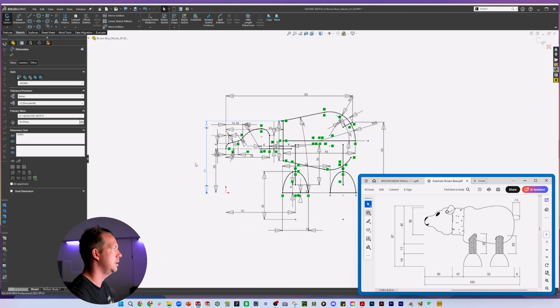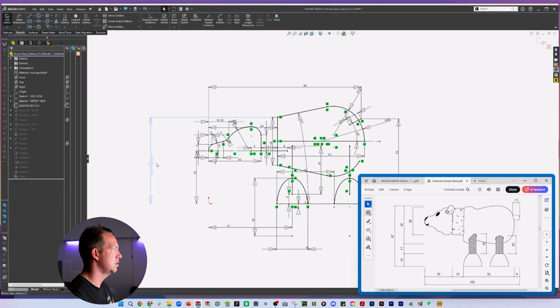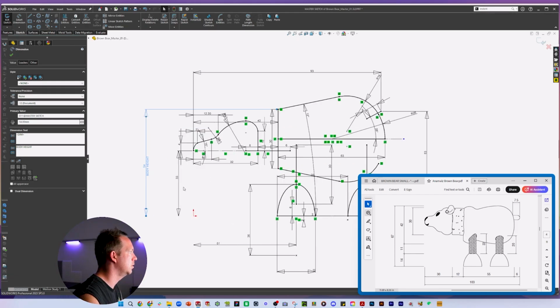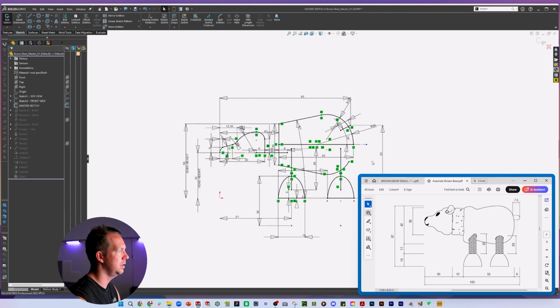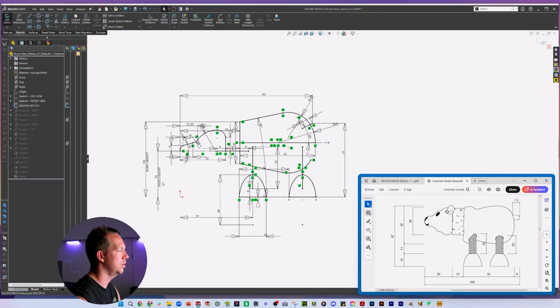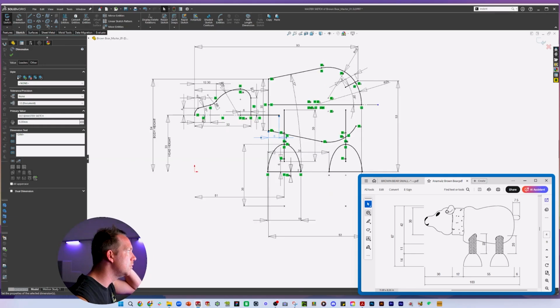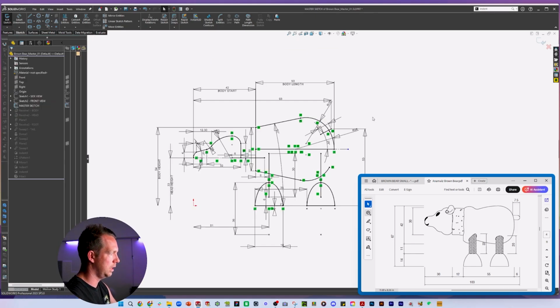So I can write in that sketch here, body height, and see it has notes in the sketch. So I know that that's controlling the length or the height of the object. We can look at this one here because this is controlling the head height. The length, do we want it a bit longer? Maybe. So what's controlling the length of our animal? Well, it is the starting point of the body. I'm trying to find where that dimension is. 42, body start. Got body start, and then I've got here, body length. So just those key dimensions.